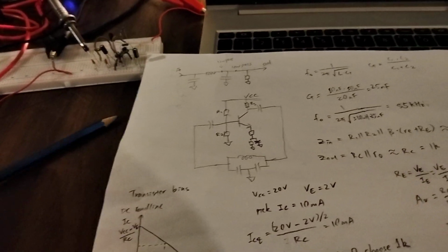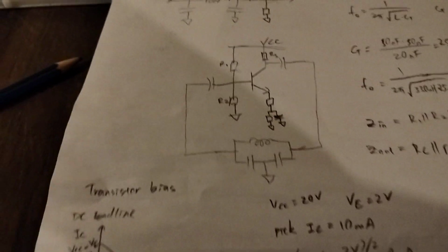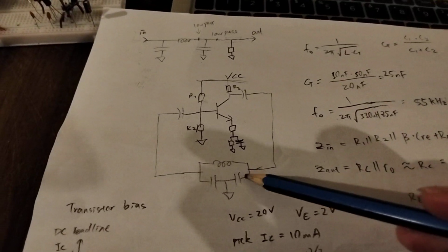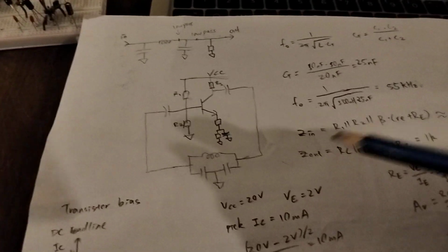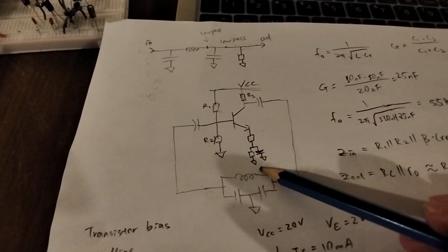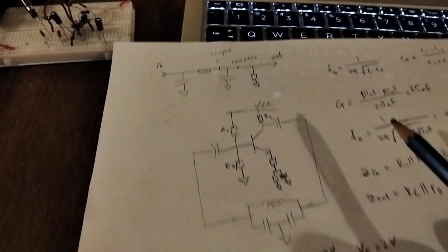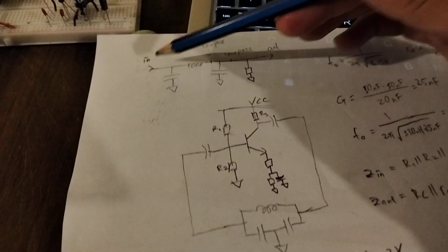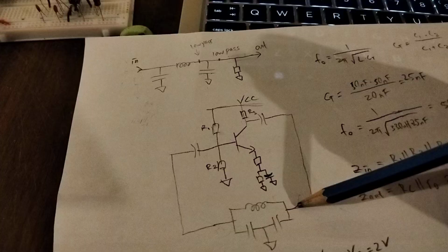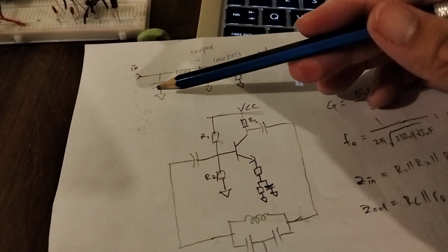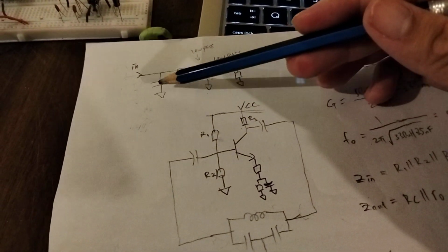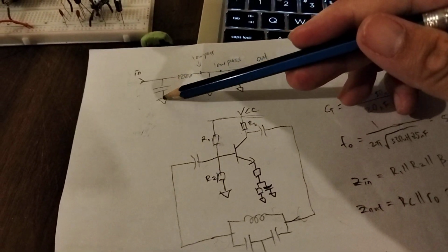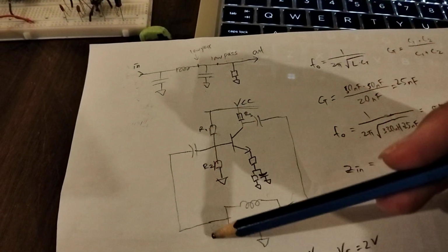So I just want to quickly go over what this oscillator actually is doing. Specifically, what is this filter here? Because it's a weird looking thing, and it's actually just drawn weird. What this filter really is, is what's up here. You have an input voltage, in this case coming from this side, and it goes to a resistor to ground, and then an inductor, and then a capacitor to ground, an inductor, another capacitor to ground here.